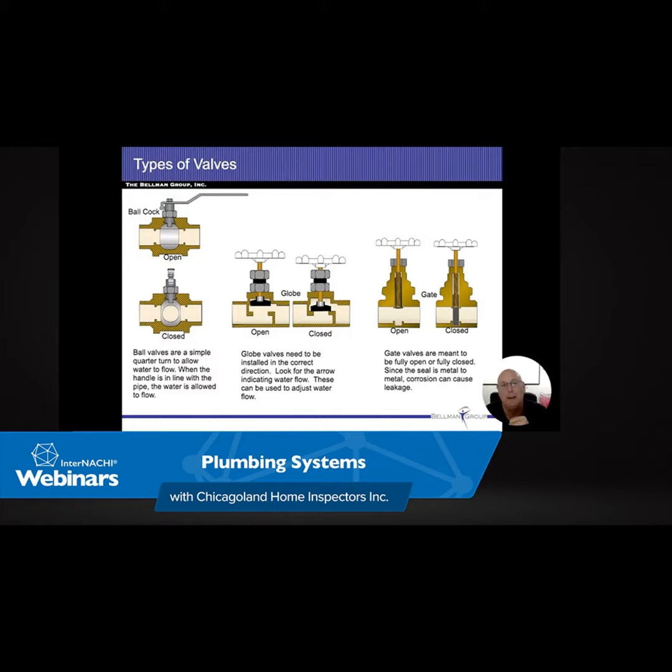We'll go into the other numbers, what's normal, in a second here. We're talking about the height now. So if we start off with a 60 psi service coming in from the basement, we go up 1 floor, we can expect a 5 pound loss, is what they're saying here. And that's just an average. And again, we don't really measure the pressure itself. I just want you to know what that is.